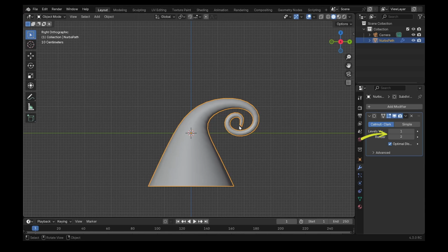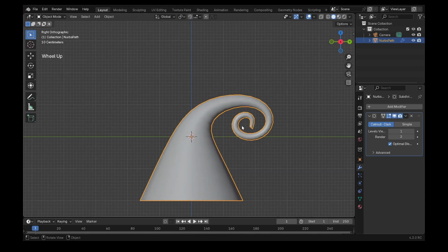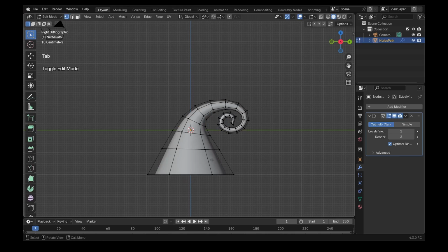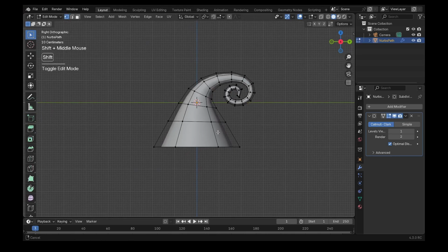Now you may be wondering, we had the option to change resolution in the curve properties as well, but instead of increasing, we actually decreased the value there. The reason being, we knew we will be converting the curve to a mesh object, which would have made the geometry permanent. And editing a high-resolution geometry is generally not ideal. But with our Sub-D modifier, the base geometry still has that low resolution, so it's much more convenient.